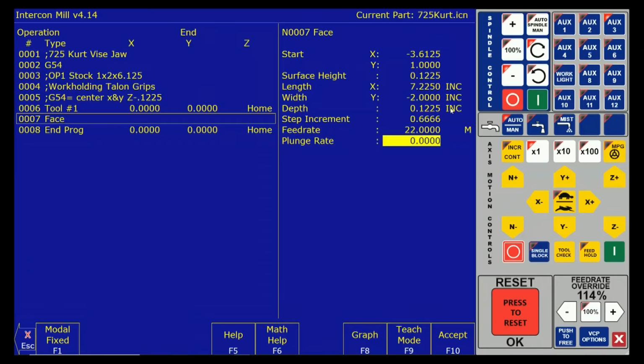Now here's where you're going to have to take all of that information with a grain of salt. The manufacturer will give you a range, and that might work for you. On these machines, we're using bed mills that have seen a better day. We've got some runouts in the axes. We've got some bearings maybe in the spindle. The rigidity of my work holding, the rigidity of my cutter, I might not be able to cut at manufacturer's recommendations. A program is only good until you hit cycle start. And then the setup machinist is typically going to need to adjust his program.